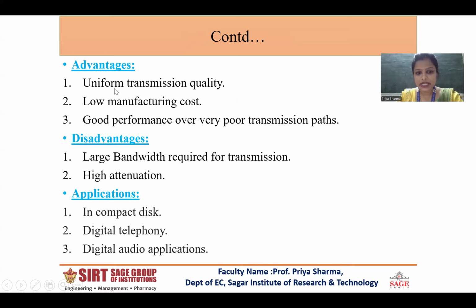The advantages are uniform transmission quality, low manufacturing cost, and good performance over very poor transmission paths. The disadvantages are that a large bandwidth is required for transmission and it is prone to high attenuation. Applications are in compact discs, digital telephony and digital audio applications.